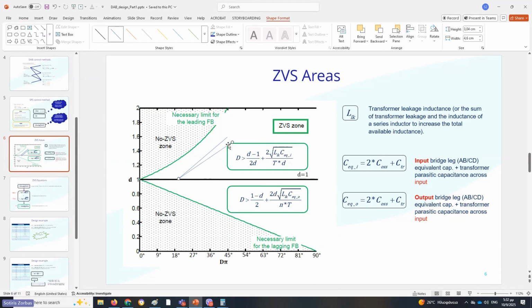If you put the leakage number and everything, you'll have something like that. And this is the low power output. Imagine you'll play from 20, 30 degrees, the lowest power to achieve ZVS, and then you can go higher. And of course, at full load, you're going to have ZVS. But the worst condition is approaching a few degrees, so low power.